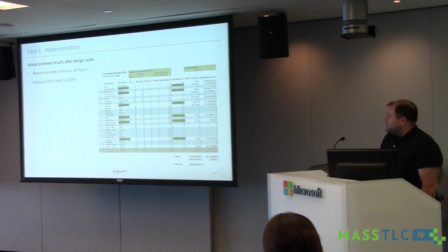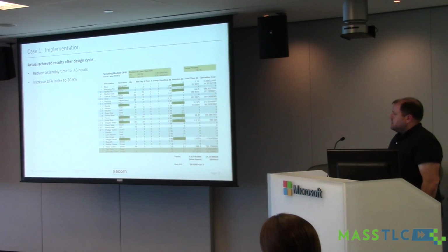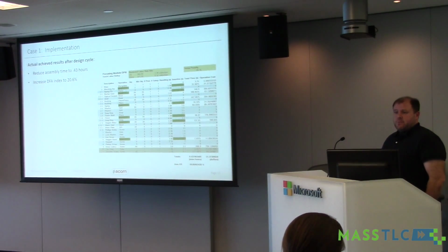and I won't go into lots of detail on them, but obviously snaps, better alignment, self-aligning parts, removal of hardware, single-axis assembly, you know, all of those checklist items we'll implement as we go through. And we can tabulate out a bunch of these different solutions here on what do we think is the right mix. Each of them have a different ROI aspect to them.